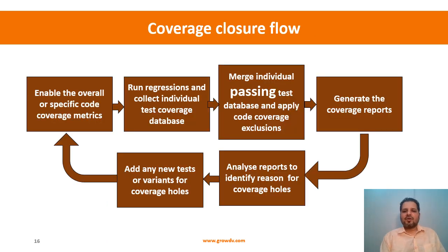So once you have implemented the coverage model, and then you have the implicit coverage generation flow in place, which is nothing but enabling a few options in the simulator, and then you have implemented a functional coverage model and integrated it into the test bench, and you are able to create the metrics to look at how the verification is progressing. Then there comes the regression debug flow, as we have seen before. There comes a point where we need to march towards sign off, wherein you want to tape out and create a chip.